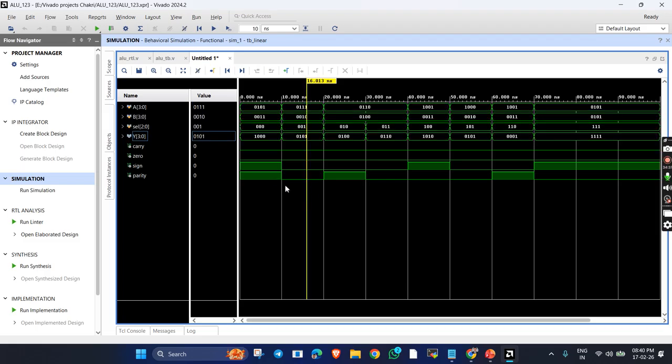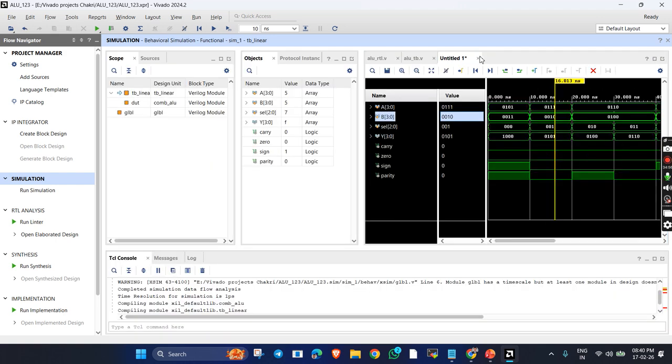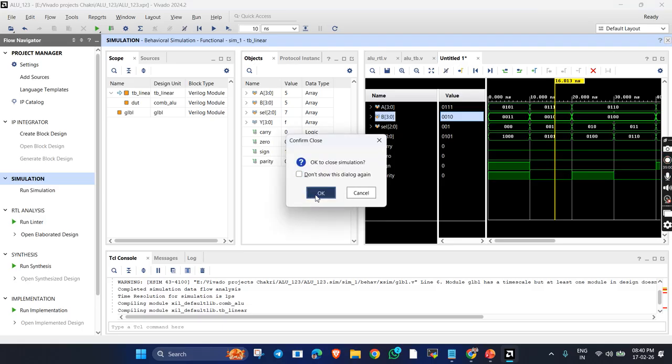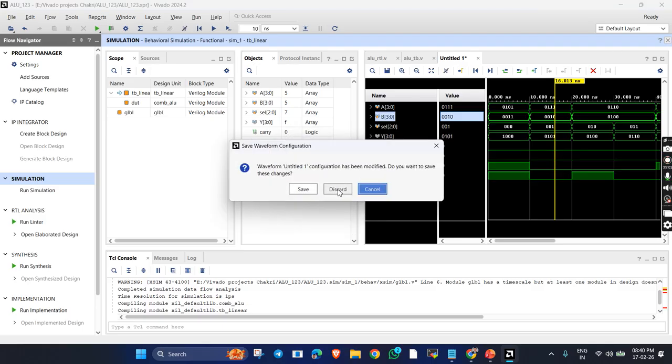If you are working with binary, you can easily understand the binary values. Since we are declaring it as multiple bits, here we are declaring it as a vector, and we are passing the values in binary also, so you can easily analyze it in binary. Like this you can change the number systems also. So this is the simple process of simulating the design, and we'll go for the next test bench, that is the task based test bench.